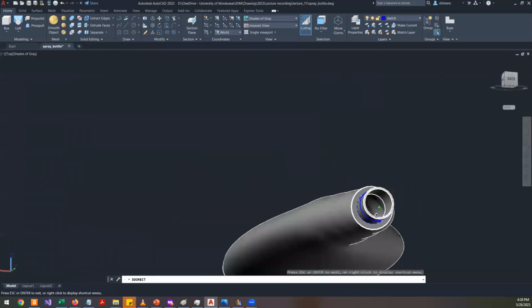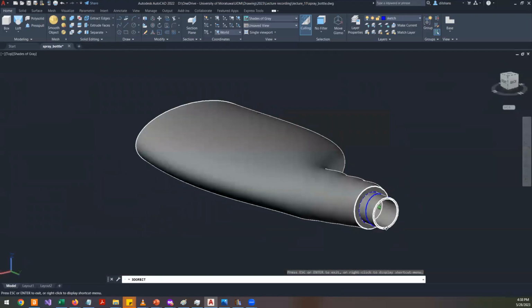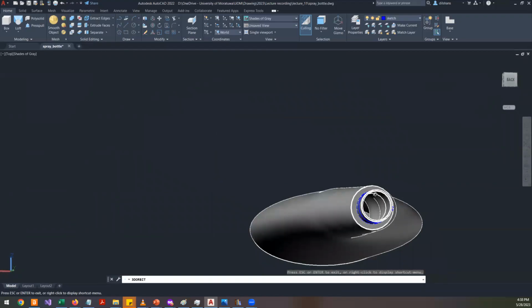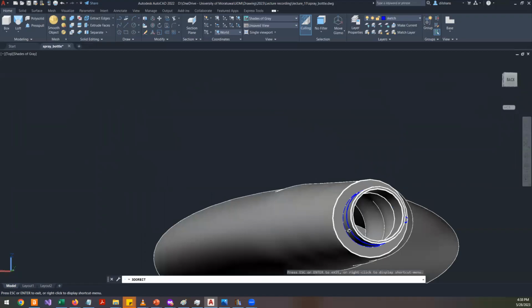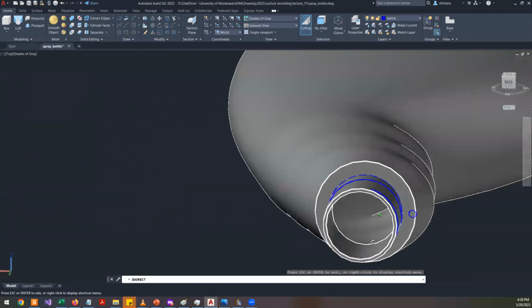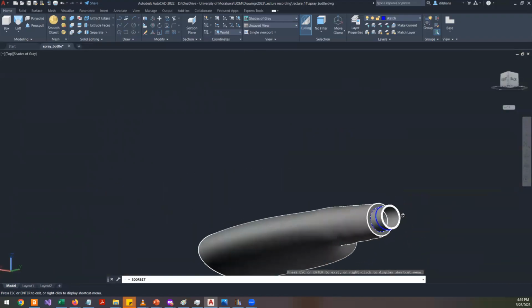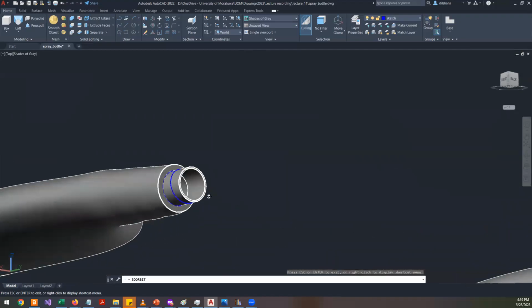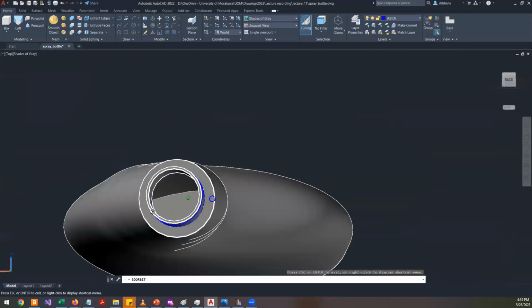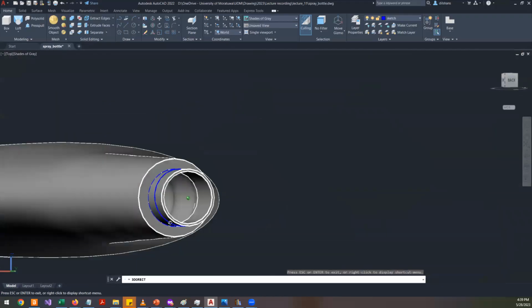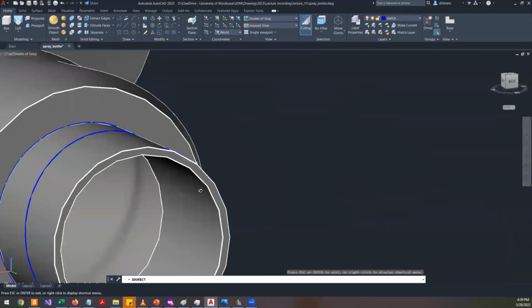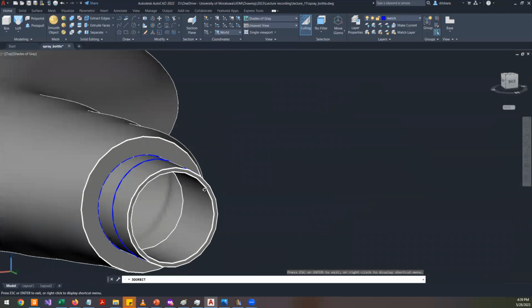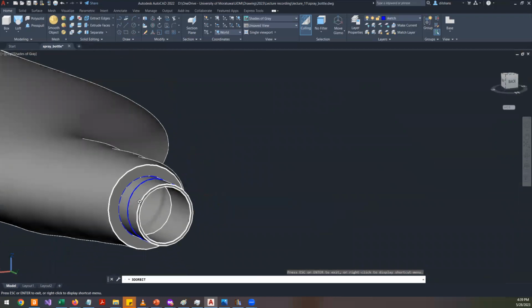Finally, I did something like I combined the top part with the bottom part, then applied what's called a shell operation, where you are removing the material. So initially, we have something like this. So after shell, you have an empty container. So you can define a shell thickness like 1 mm, 2 mm, or whatever the accepted value, and remove the internal material.